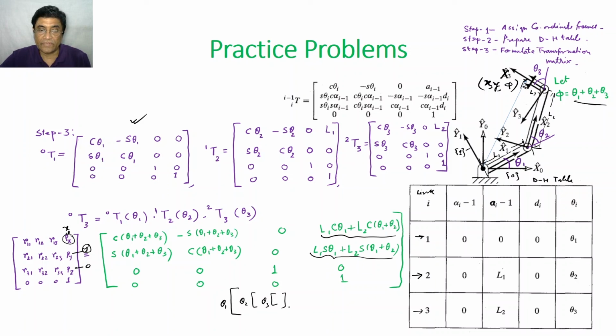So that range you can put over here, range R1, R2, then a different range, R1 prime, R2 prime. If you know the ranges, you can calculate this matrix, and that will be actually huge data. The forward kinematic solution lets you calculate the working envelope of the robot. Using inverse kinematics, you can command the robot to go somewhere, and eventually we can control it.